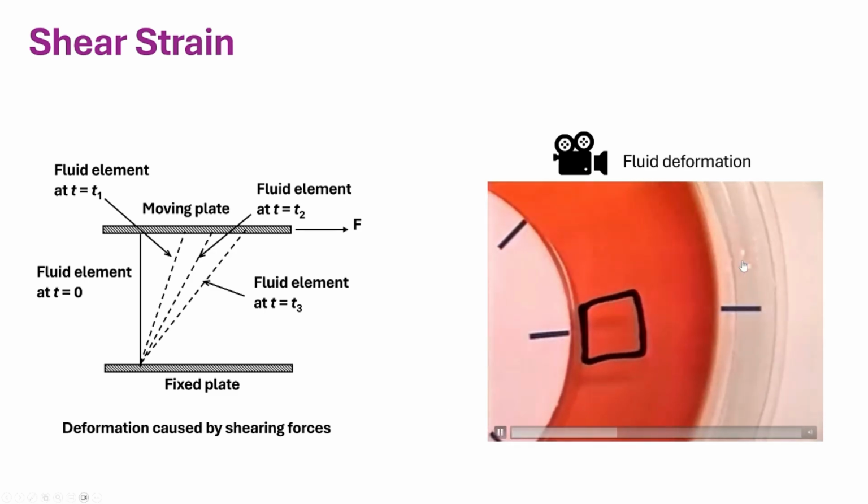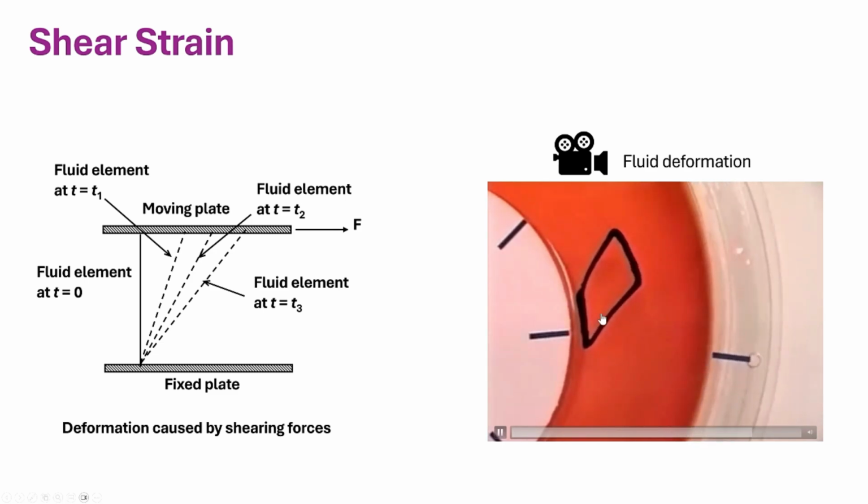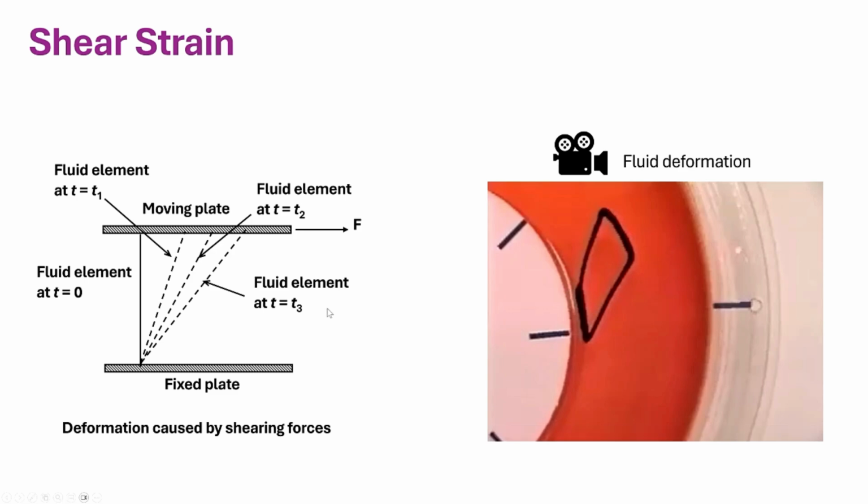As this plate starts moving, you can see how this element inside this fluid deforms. And on the edge here, we have no slip conditions, so no deformation. But as long as this plate moves, we will have displacement or deformation of fluid elements inside here.